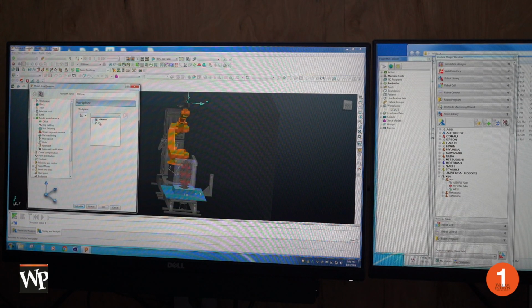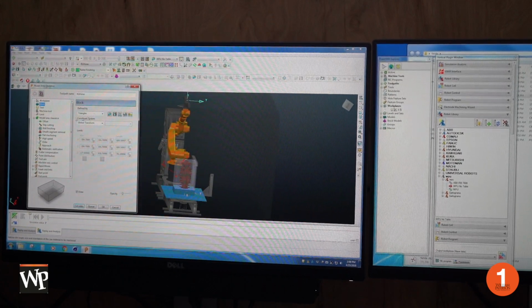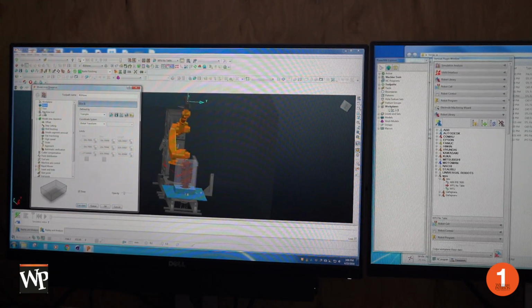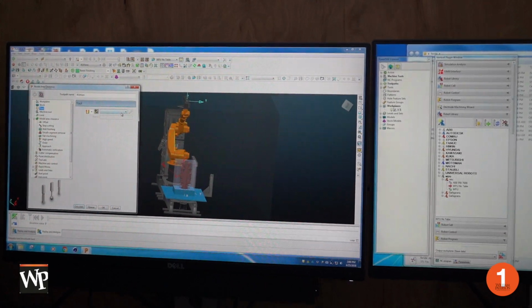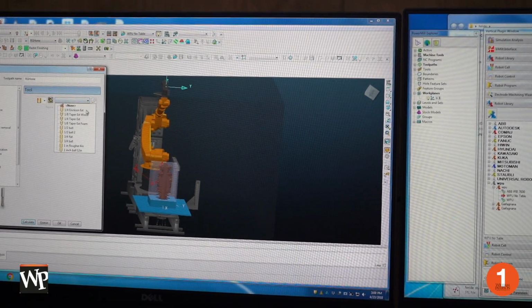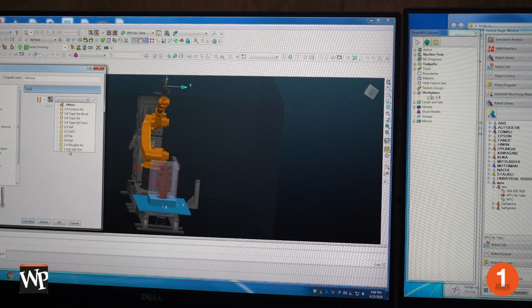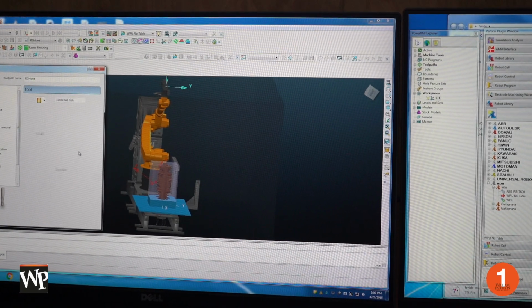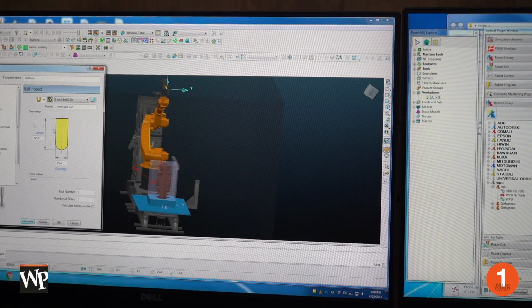So now I'm going to choose work plane 1. Our block we've already defined, that's good. Our tool, now we have to choose our tool. To do roughing, I'm going to use our 1-inch diameter, 12-inch long tool, the biggest, longest tool we have.